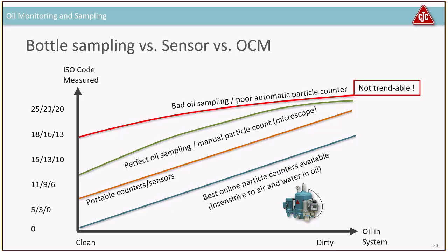And when the pitch is not in operation, when the turbine is standing still, of course you're getting very, very clean oil. So yes, you're getting close to zero particles. Of course you are. You have an efficiency of 98% in the filter, and you're circulating the same oil many, many times. So therefore it is getting close to zero.